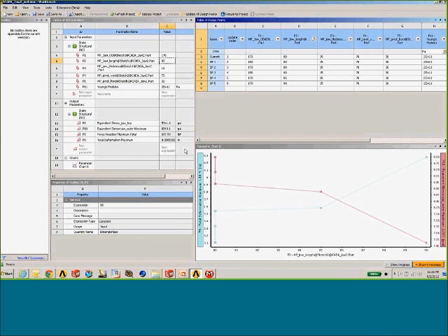Returning to our parameter set. Now, the way we're currently set up, or by default, when we kick off a group of solutions by picking this Update All Design Points setting, with a single machine, we have to wait for these to solve in a serial fashion. So each design point gets generated, submitted to the solver, and then the parameter set waits until it receives the results from the solution. It'd be nice if we would be able to kick these off and have simultaneous solutions, if we had multiple machines that we could employ.